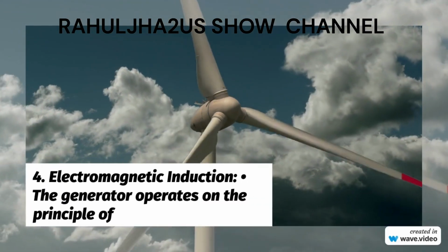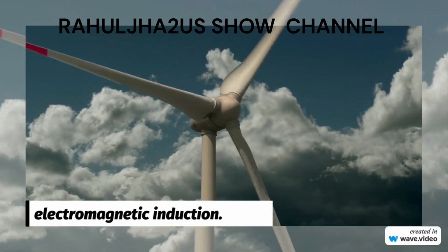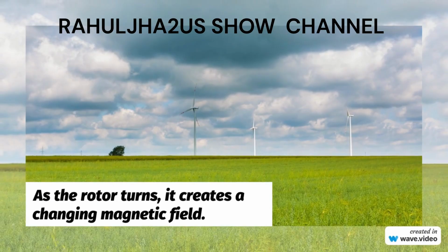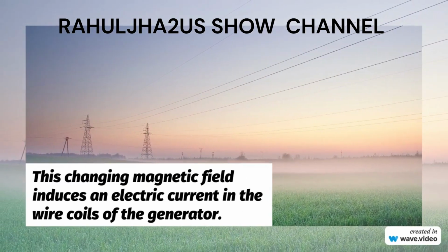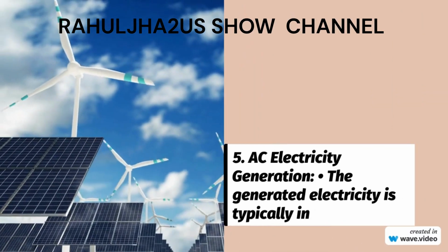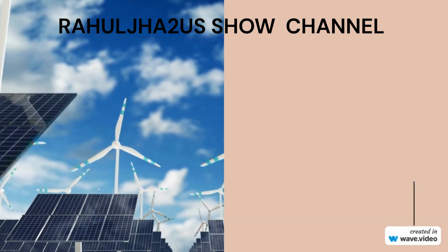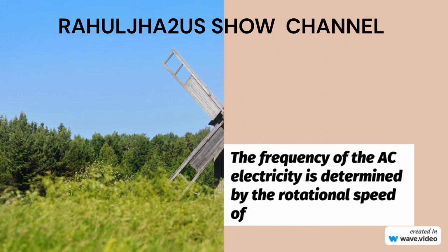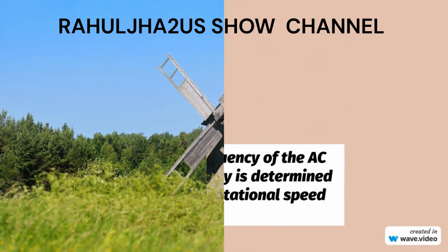Electromagnetic induction. The generator operates on the principle of electromagnetic induction. As the rotor turns, it creates a changing magnetic field. This changing magnetic field induces an electric current in the wire coils of the generator. AC electricity generation. The generated electricity is typically in the form of alternating current. The frequency of alternating current electricity is determined by the rotational speed of the rotor and the number of poles in the generator.